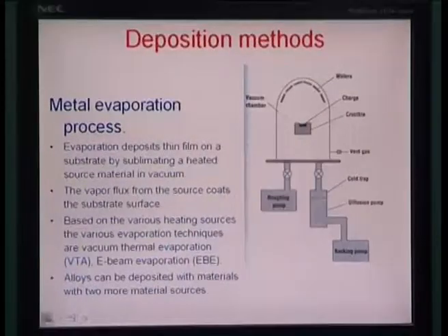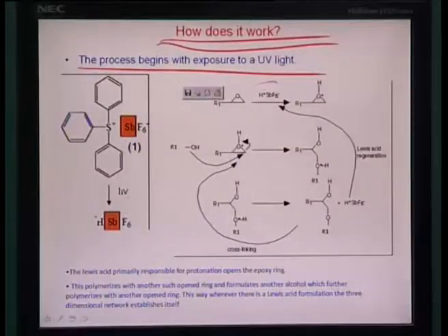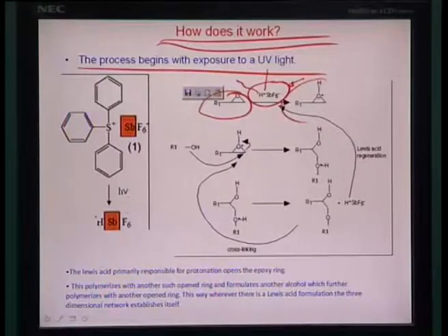So this right here is an illustration of the photoacid generator, H plus SbF6 minus. This is a demo photoacid generator. On exposure to light, it would immediately release the proton, and so the proton goes and opens up the epoxy chain in the following manner. So the first step is carried out by a positive charge onto the oxygen, and the hydrogen forming a bond with the oxygen.